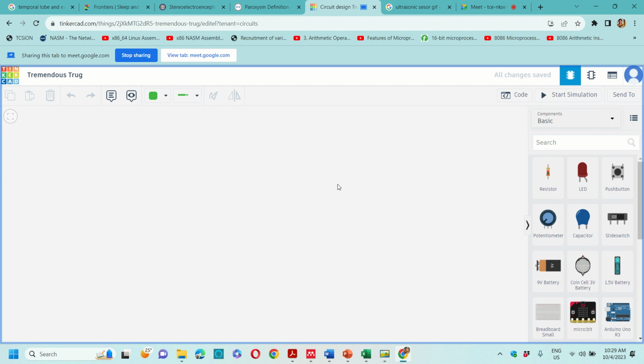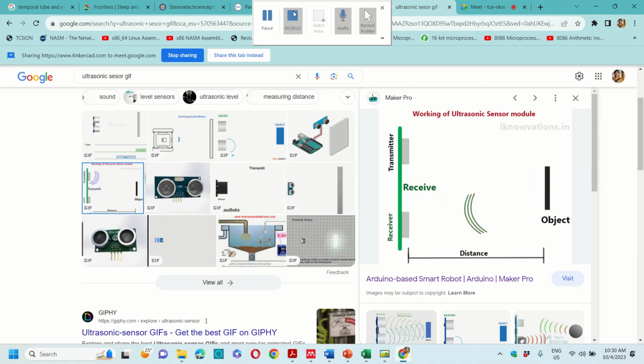Multiple LEDs cannot be connected, or we cannot provide different signals to multiple LEDs at the same time through one digital pin. This is not possible. So while creating a pattern, if I want to use 4 LEDs, then I will use 4 digital input output pins to show the output in the pattern format, right?